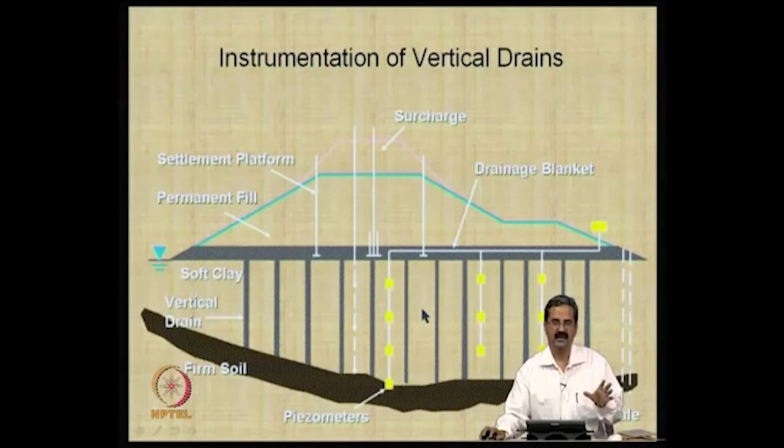Constitutive modeling has been a very powerful tool to understand all of this. Suppose an extra load is applied: how much pore pressure is mobilized, and how much settlement occurred? That is what one can do here. The way we start is that this is a pore pressure gauge, this is a settlement gauge. The moment you put some layer, for example 1 meter of embankment, pore pressures will be mobilized and settlements induced.